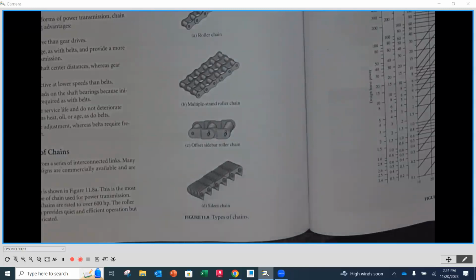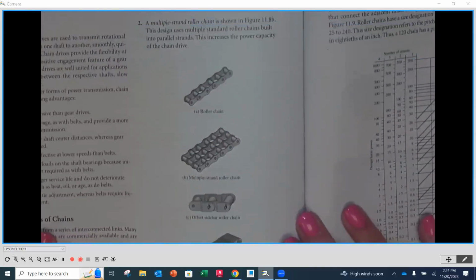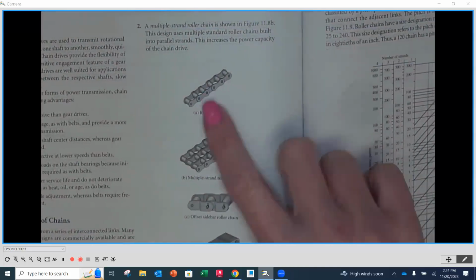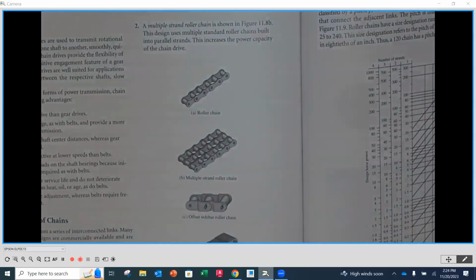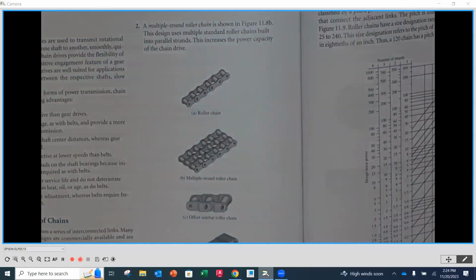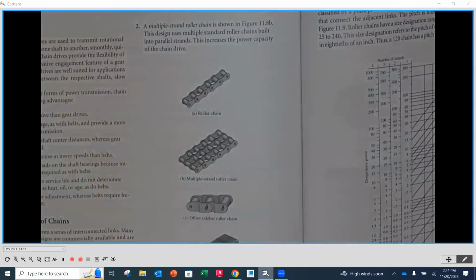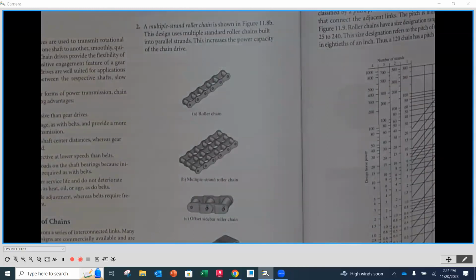Okay. Now, one of the biggest advantages of roller chain is that these links and rollers come apart. So especially when we're in an automation type of atmosphere, we can run these along conveyors and we can add different things to actually move and push items along to get to another location. Okay, so that's why they're very advantageous, especially in automation or like packaging equipment. We see a lot of chains because then we can customize those to make them fit what we want them to do.